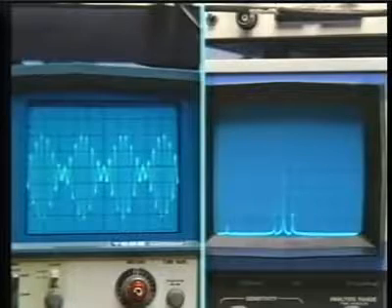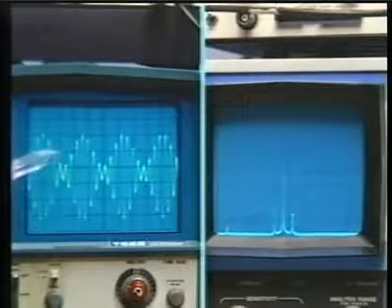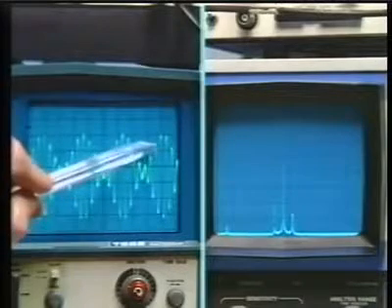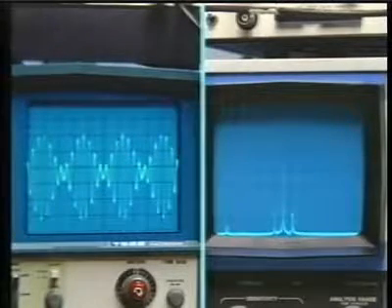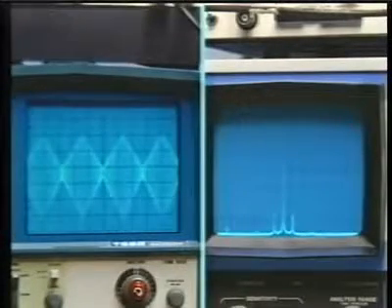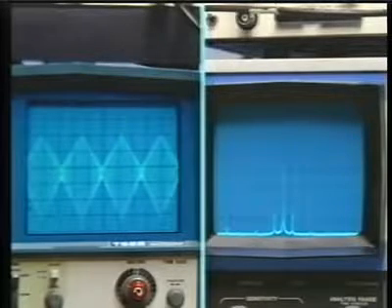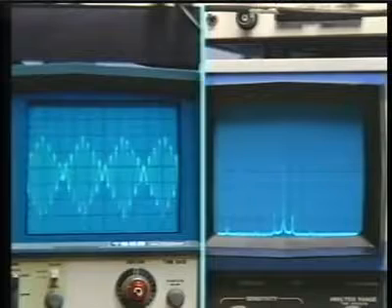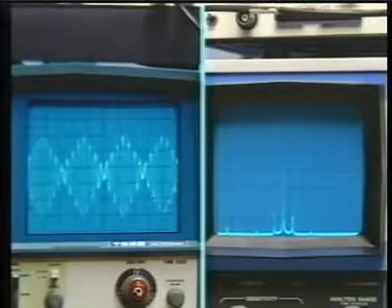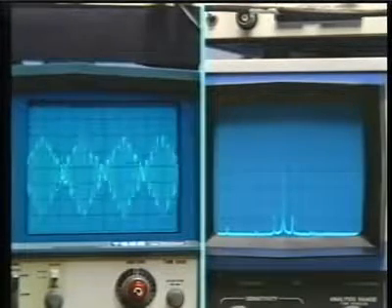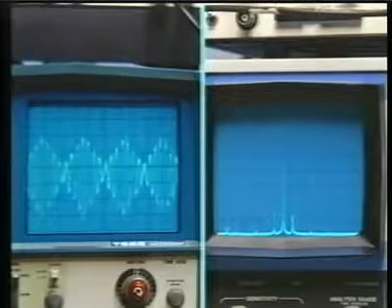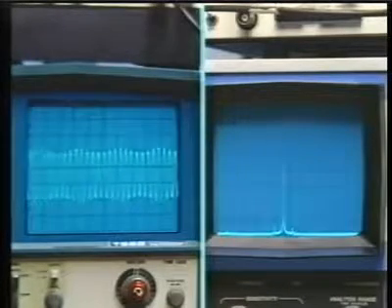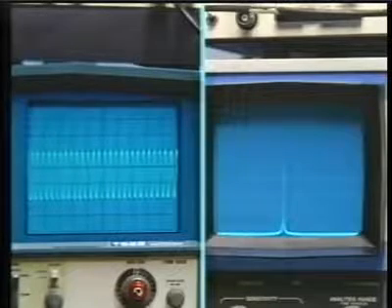Right. It's interesting to vary some of these parameters. You can see the sinusoidal modulating shape at this point. Let me switch that to a triangular shape. And again, it's a little hard to sync in both the modulating signal and the carrier, so you see the carrier kind of wandering by, but there it is. Another thing that can be varied is the amplitude of the modulating signal. I'll make it smaller. You'll see the sidebands go away until finally we have a pure sinusoidal carrier.